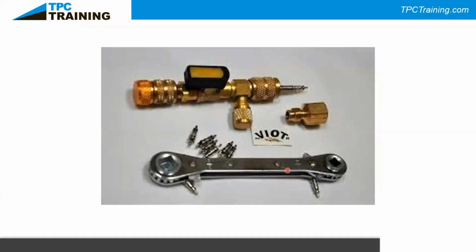On a service valve wrench itself, it's going to be listed. It might say like 1/4 and 3/8, 5/16. So when you flip it, there are 4 different sizes for these stems, depending which side you have attached on here. And then you change your setting here, and it ratchets from either left to right to open or close your service system and allow your stem to move in and out to close off the system or to open the system for us to allow pressure to read through.